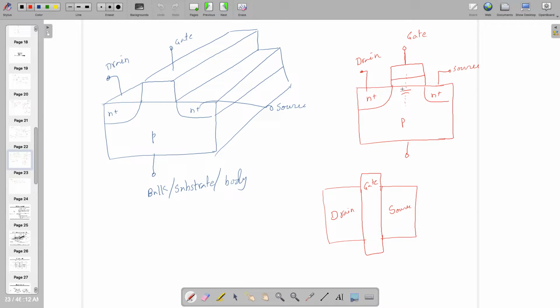So here you can see this one capacitance which is Cox. You can see here N plus and P has one capacitance. This one has one capacitance. You can name them B, D, S, and G. So you can call this one CGB, which is eventually known as Cox, oxide capacitance. This one is known as CDB. This is known as CSB. Right. So all these dissimilar metals are creating capacitance.